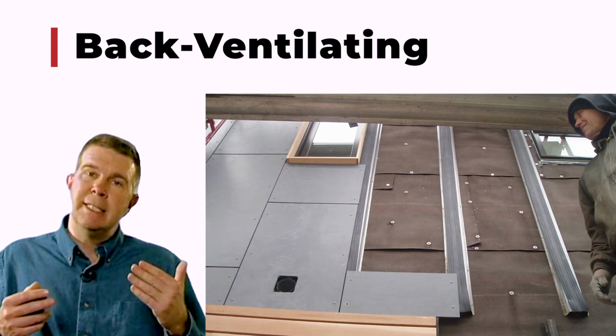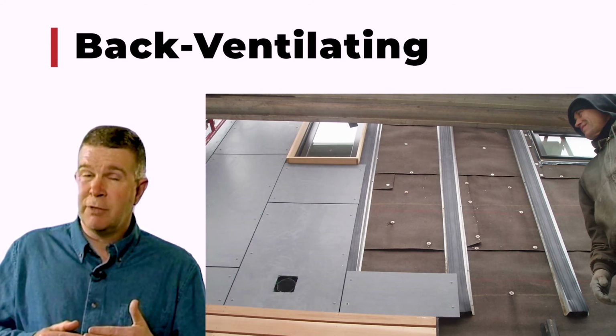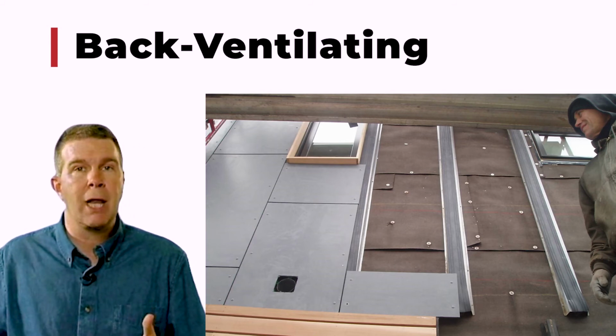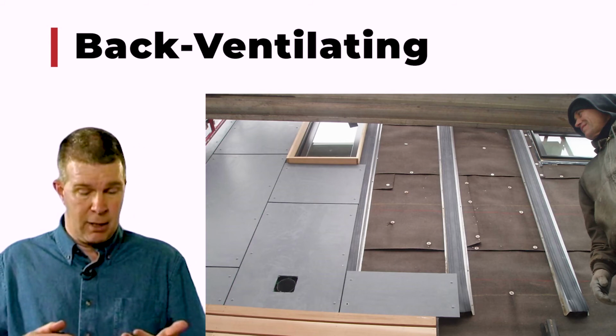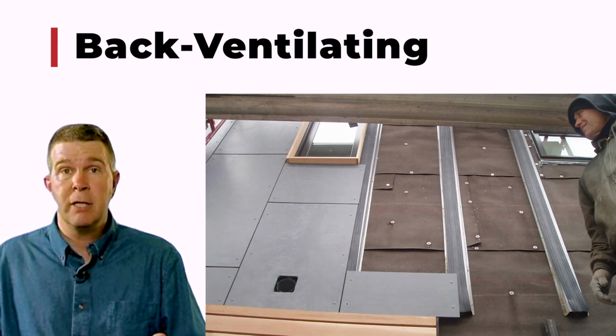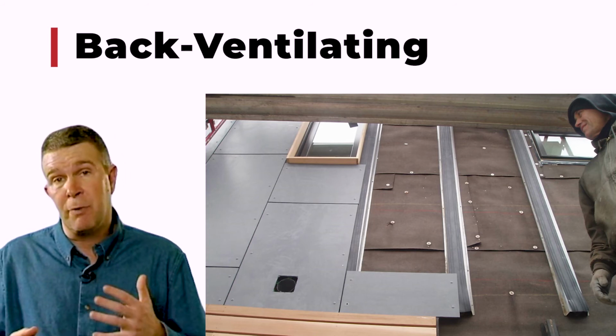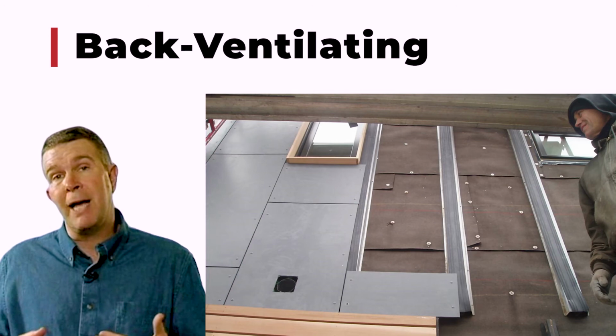Also, you need to be aware of some types of sidings which are known as reservoir claddings. What's a reservoir cladding? That might be a masonry or brick, block, stone, something of that type that has the capacity to hold a lot of water.